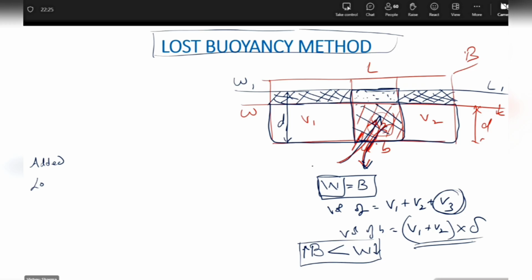So in the bilged case, it is like the mug being kept inverted, and now the water is filling up in the compartment and is not getting displaced. If the mug was upright, it was displacing the water. Why? Because the volume going into the water was intact. And when you put it upside down, it just goes into the water, because the water will keep filling up in that space and there is no displacement of the water which is actually taking place. Guys, please let me know if there is any more thought coming to your mind. Understood, beta?